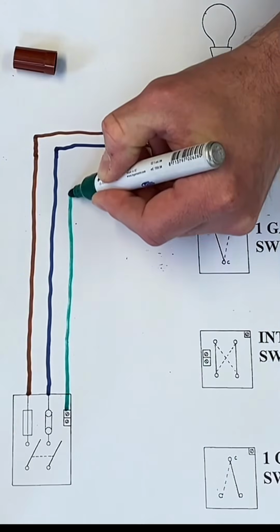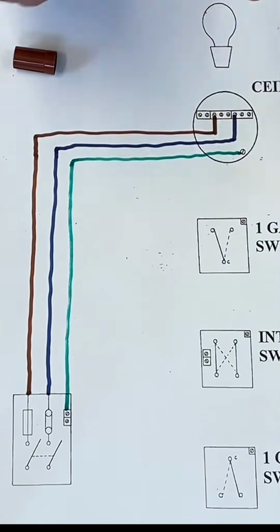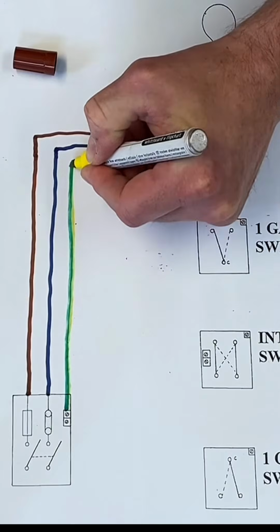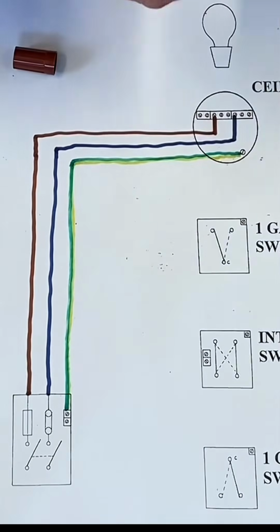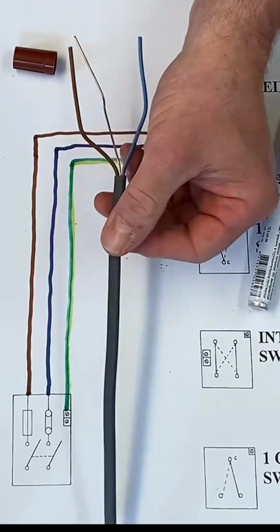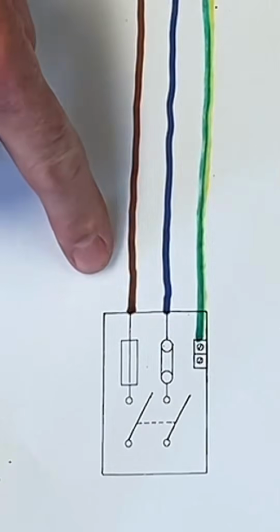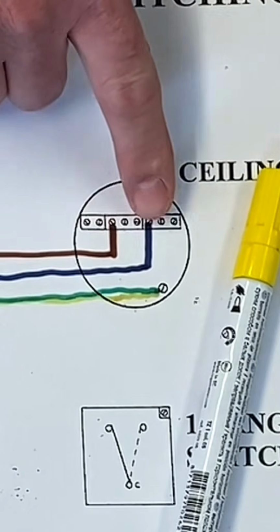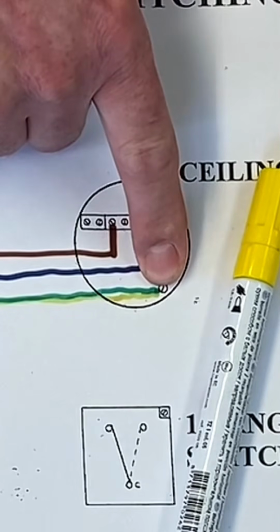So let's bring the CPC in, like so. And again, some of my learners do like to just put a slight strike of yellow down there. It's still only one cable. It's not two cables now because I'm doing two lines. And then it becomes my CPC. So what we've done there is we've brought in from the consumer unit permanent line, neutral and CPC, line, neutral and CPC. We connect it into the looping terminal for the line, the neutral terminal for our blue neutral conductor and the earth terminal for our CPC.